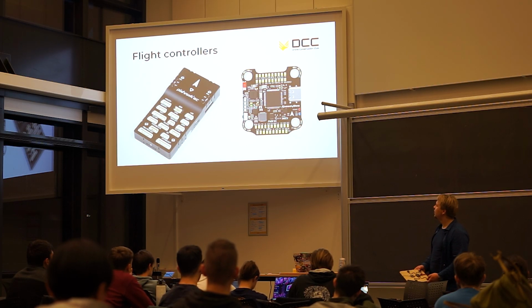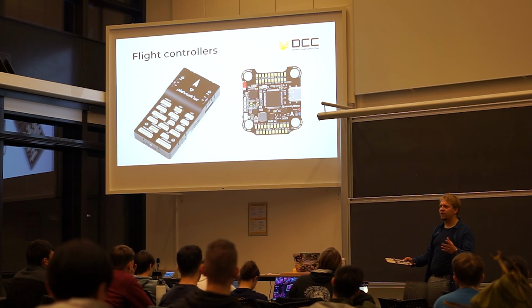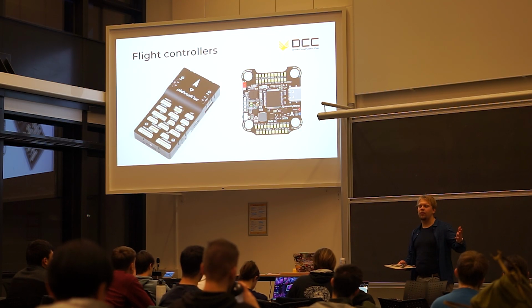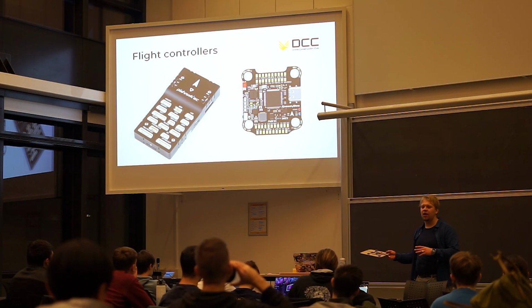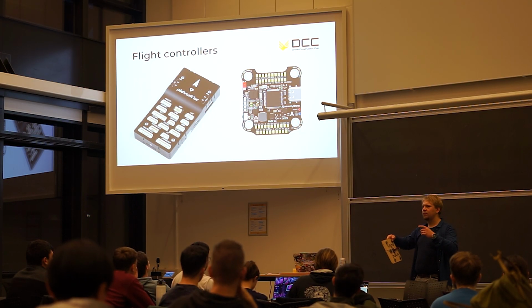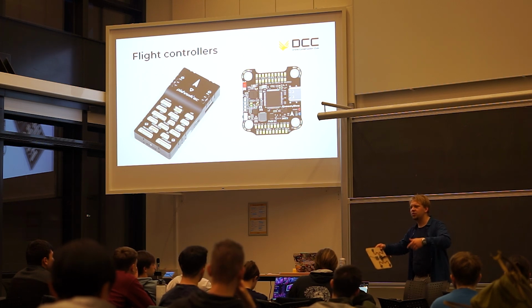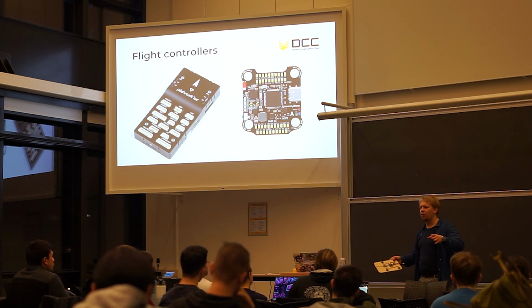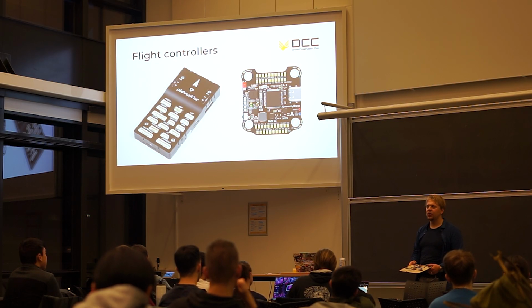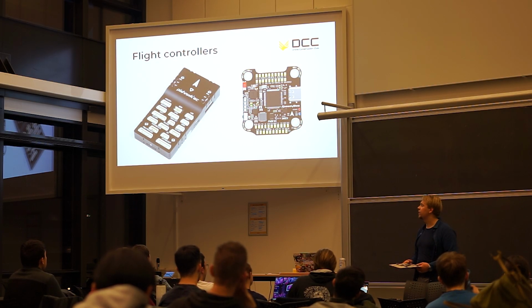Quite often for communication, you also want to use I squared C. They also have those ports. You usually have different sensors that use different protocols for communication, and you can set all that stuff up on the computer. You either choose the firmware which can do what, or you change parameters in the firmware to be able to do different communications with different ports and so on.